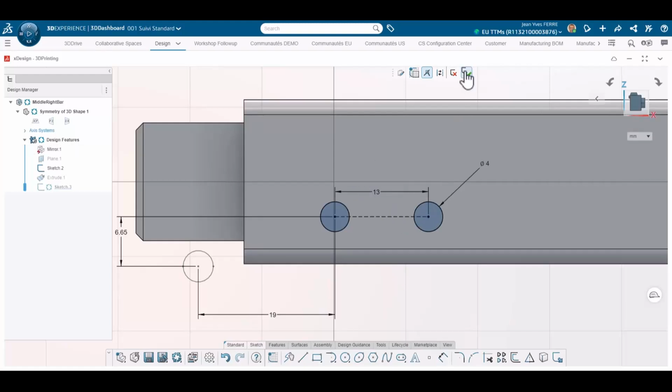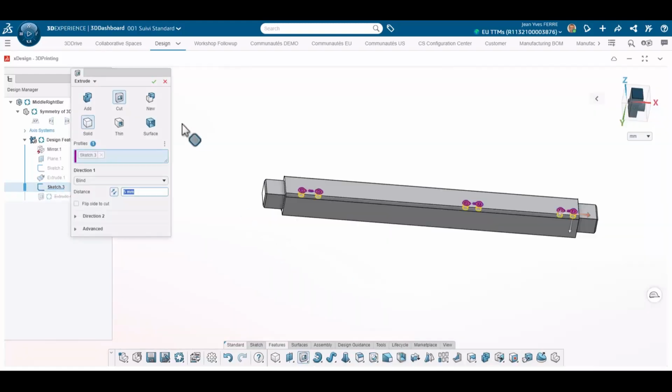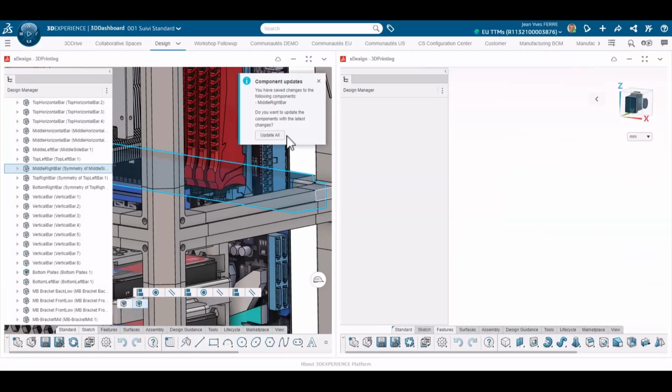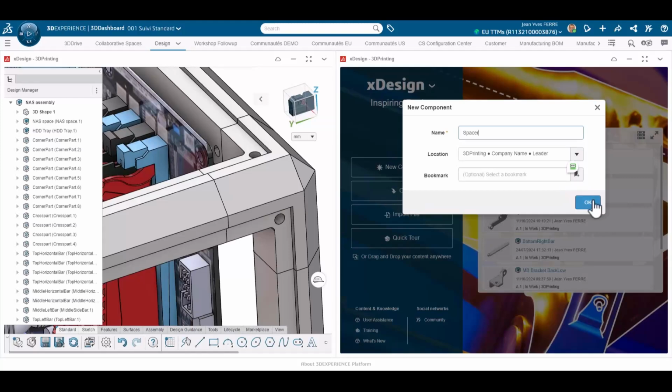Here I changed the last spacing to increase strength. Torque was more important because of the cantilever. Once holes are made, the middle part is ready for threaded inserts. Now let's design spacer columns to finish up the assembly.